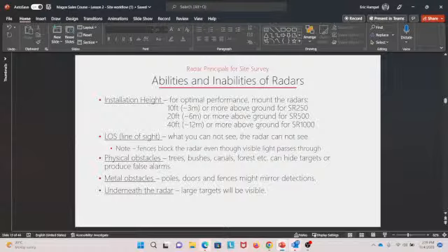So therefore as well, if you want to cross-check with us, take pictures from the position where the radar is mounted. If you have subcontractors putting the poles, and you would not be on site, make sure they will share a photograph before they start digging, so to speak, because one more time, things might have changed, and the end customer did not update us, you, the plants, whatever.